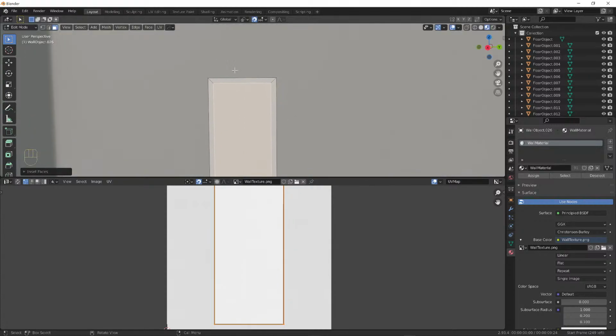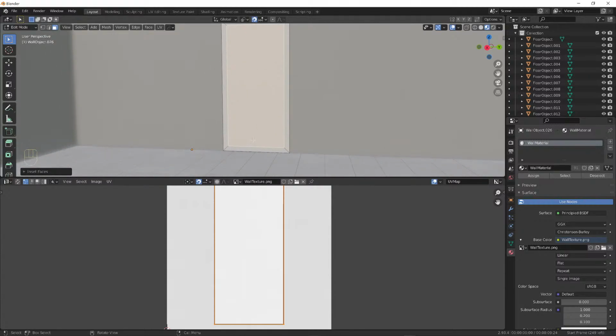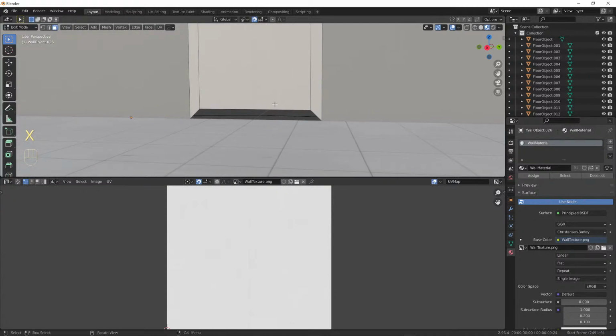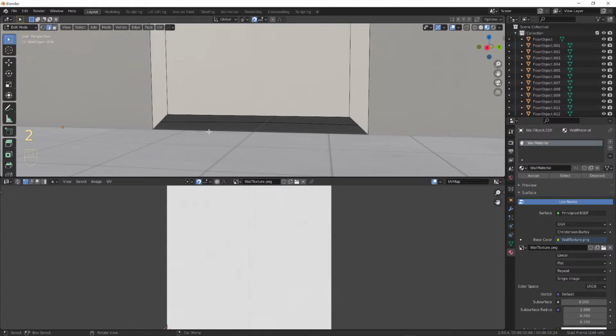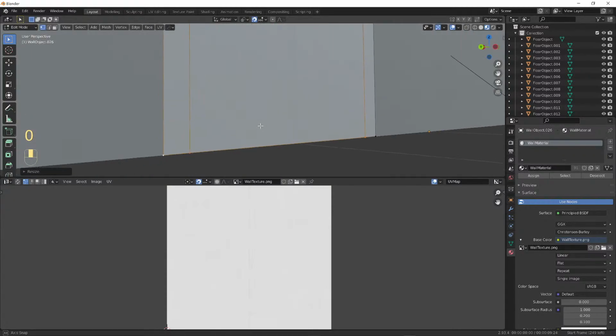And what I'm doing this for is to get this nice door frame geometry here. I'm going to select this face down here. I'll press X to delete that face. And I just want to move this edge here down so it's level with the ground here. So to do that, I'm going to go into vertice mode with my pivot point set to active element. I'm going to select one of these points at the very bottom. And with these two selected also, I'll press S, Z, 0, and it'll snap those to be level with the ground.